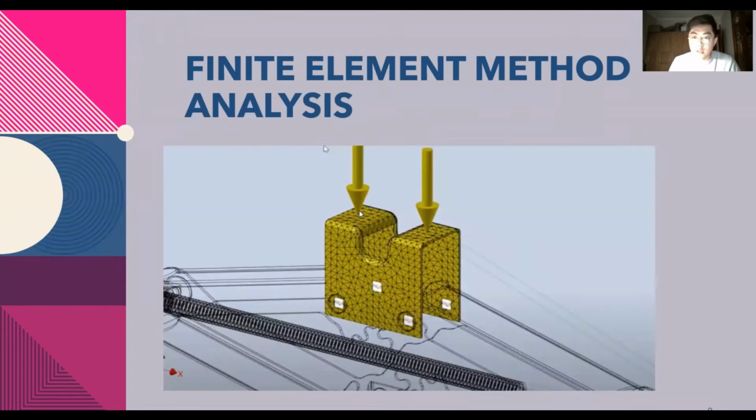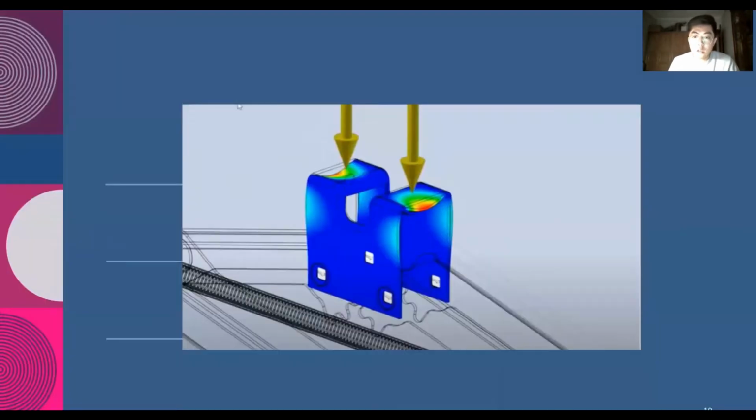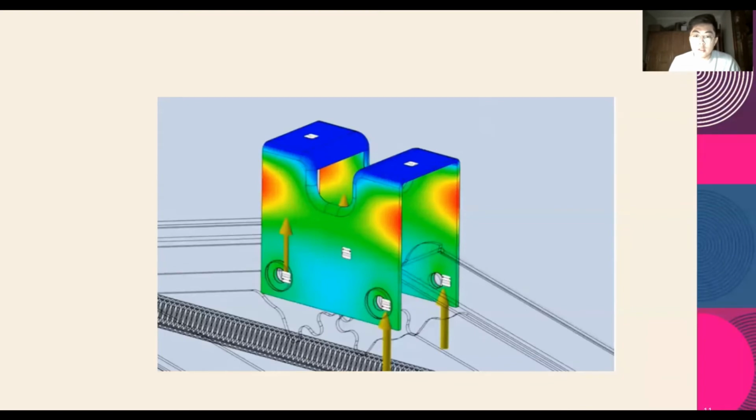So for the analysis, we are going to put a load of the car on this left pad on the jack, and then we will analyze the left pad. We have put a 1,000 pound total load on here. This can be seen in this figure. Then we run a simulation of the bending in this area. It's shown in this figure. Finally, we do a dynamic simulation with motion load analysis. We have to put a motion load for each of these components at different time steps. That's all. Thank you.